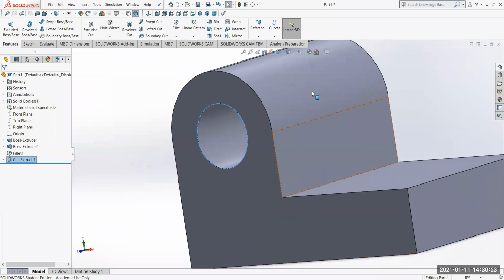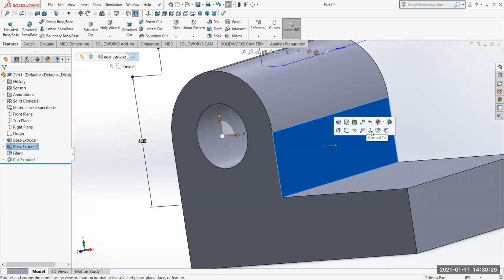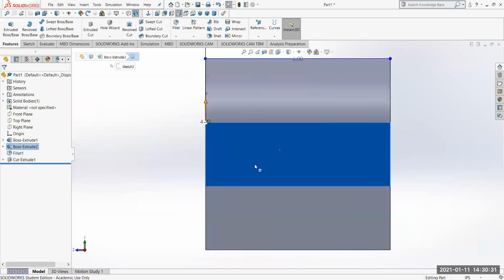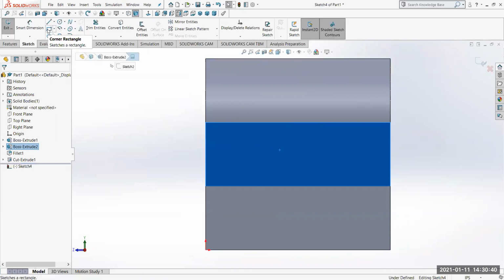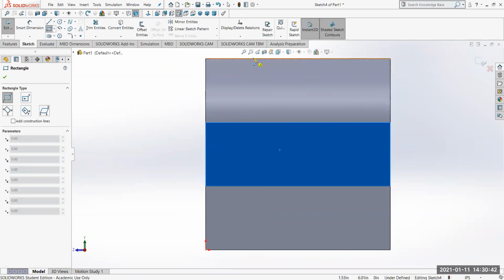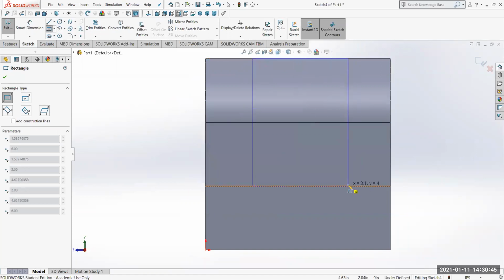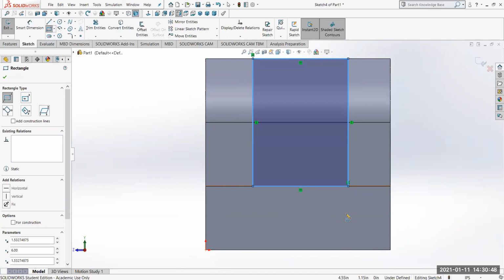And now let's cut this thing so we have a hole in the middle here. So let me go to this piece, normal to this, and we're going to cut right here. We're going to cut this rectangle out. So I'm going to go extrude cut with a rectangle, and just somewhere on this top edge and somewhere on this bottom edge. Okay. And it's going to be 4 inches wide. I have the bottom set, I have the top set. I just need to make sure that it's 4 inches wide, and I have to tell it the thickness here is going to be 1 inch and the thickness here is going to be 1 inch.